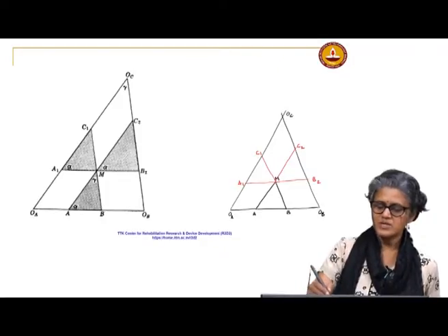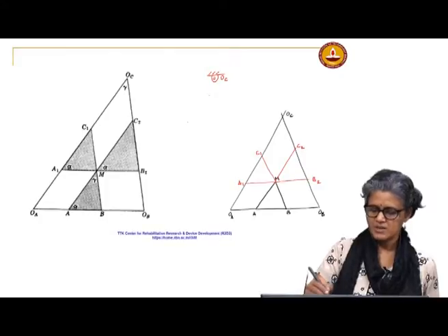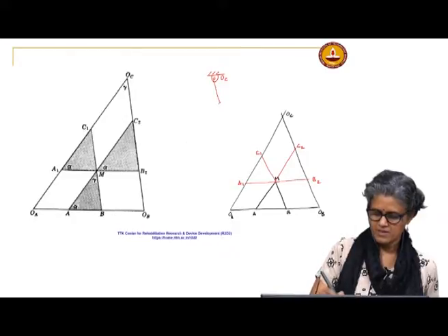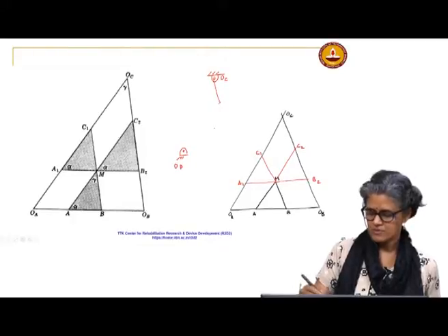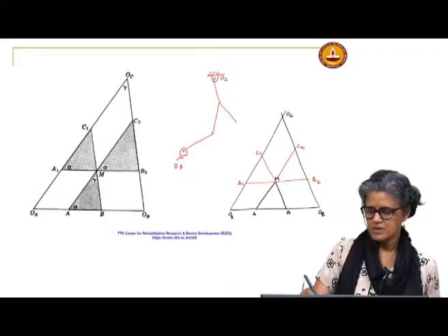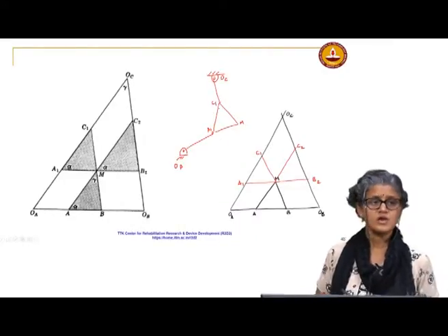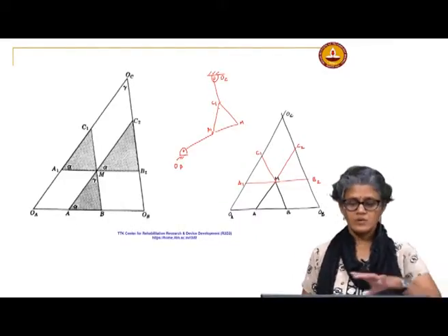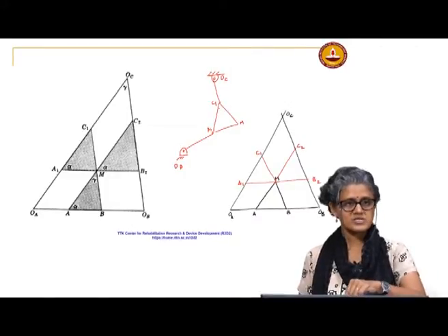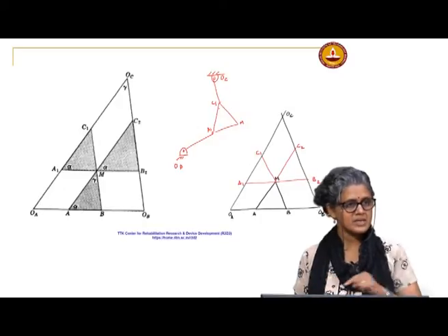And then when you construct it, if this is the actual location of OC, then you know your C1 may be here, and this will be say the actual location of OA. So, A1, C1, and this would be M. So, your actual link would be something like this, the cognate. In space, it would be located such that it is at the actual locations with link lengths obtained from the Cayley construction.